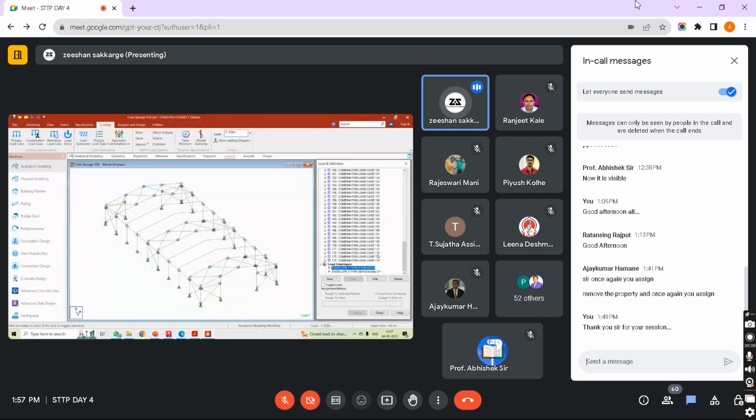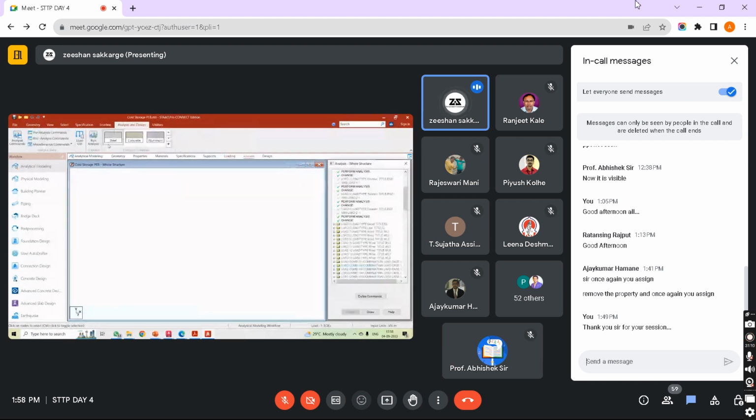We prepare the envelope based on the strength criteria and next envelope based on the serviceability criteria. Because for strength and for serviceability, we have different load combinations and factors are different. For serviceability, we don't consider the factor of 1.5. For strength, we consider the factor of 1.5. We include dead loads, live loads. For everything, we have different load combinations as per our code. So when I run this, let's also run this.